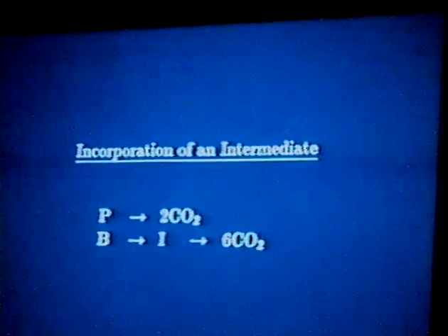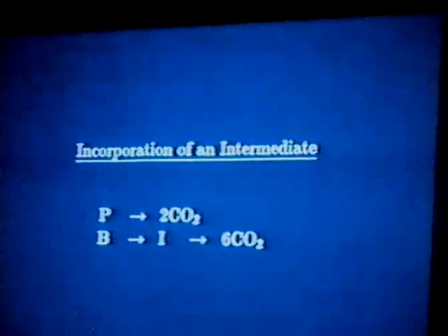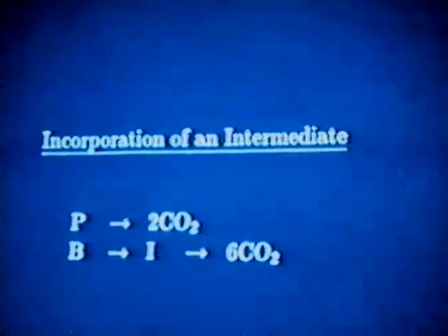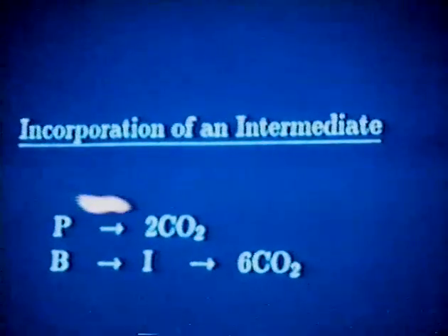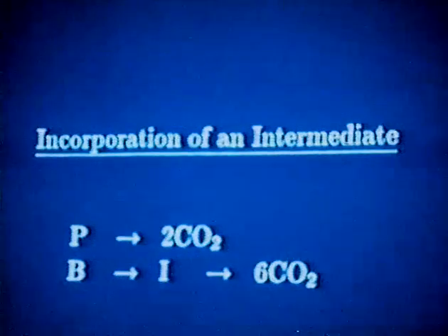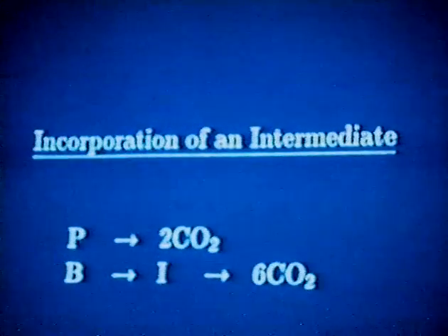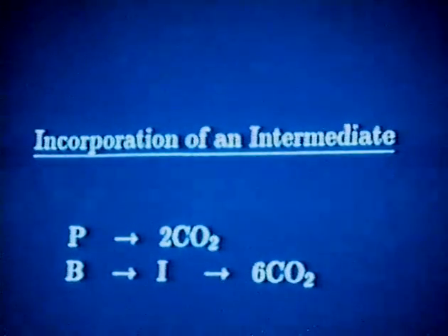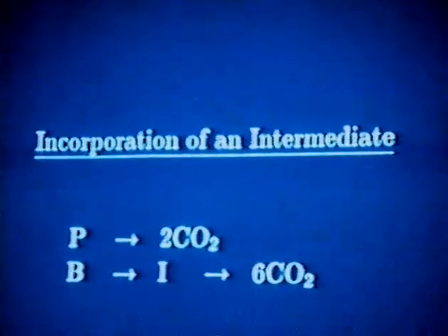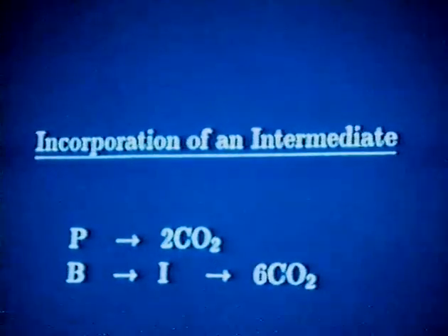In order to correct for this, we incorporated an intermediate term in our model based on the following simplified stoichiometry. Again, PCE was assumed to degrade rapidly to the 2 CO2 molecules corresponding to the 2 carbons in perchloroethylene, as well as the HCl. Benzene, on the other hand, was assumed to go through some intermediate species, which is more likely a series of intermediates, before it eventually formed these 6 CO2 molecules. We assumed in this derivation that the total amount of intermediate and benzene in the reactor never exceeded the initial benzene loading. That is, the degradation was a stepwise or series fashion.